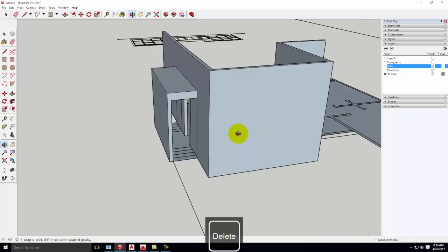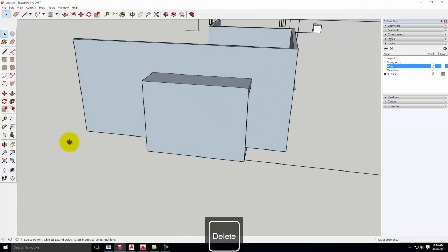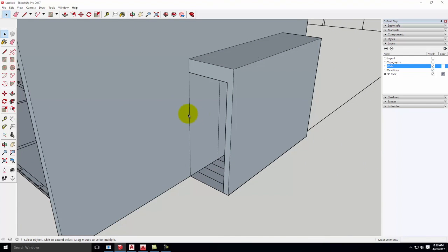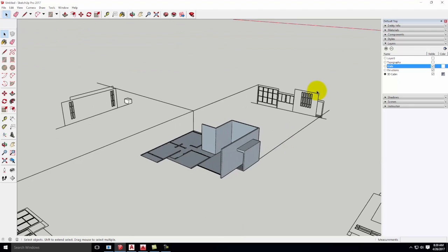And so you can see how I was able to create this little alcove by using a combination of my AutoCAD drawing. It's not perfect. In the world of Rhino, for example, we can bring these drawings in much like I did. But we can use them to do projections, and suddenly you have it all on your object. It doesn't quite work as clean in SketchUp. Generally, it's best if you leave these as components and then trace over them to build your various shapes. It's still a lot better than drawing it from scratch. You have something to trace, and it's relatively easy to build the pieces up.